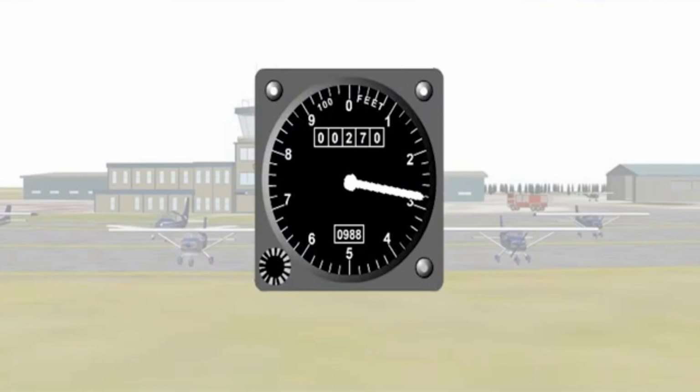The following checks of the altimeter should be made before flight. The instrument dial glass must be clean and undamaged, and the correct altimeter setting must be set on the subscale. Air traffic will pass you the correct altimeter setting, and once you have it set, you can check that the altimeter reads within plus or minus 50 feet of the apron elevation. The apron elevation should be displayed in the Airfield Operations Center or, alternatively, it may be marked on the aeronautical chart you are using.